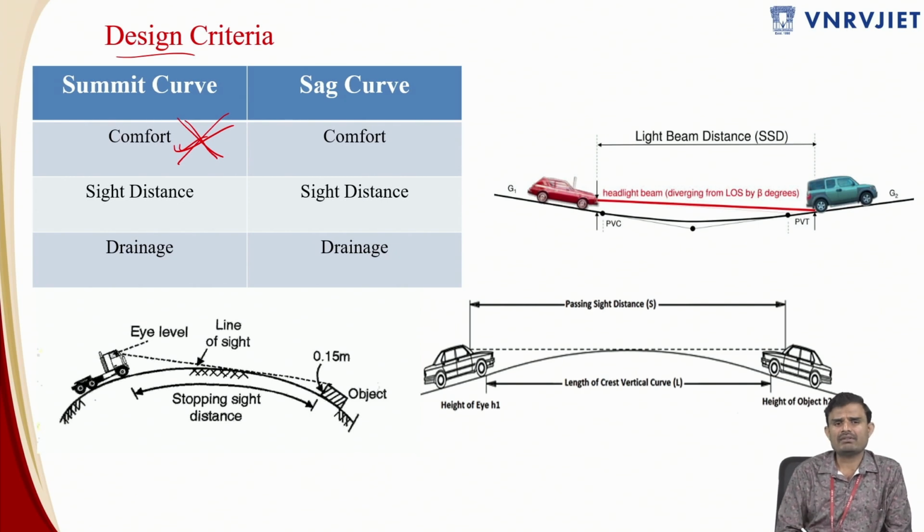Whereas in a sag curve, we are not feeling comfortable because of the self weight of the vehicle plus the centrifugal force which is acting onto you. So both of them make you feel uncomfortable or less comfortable. So you have to design for comfort criteria.